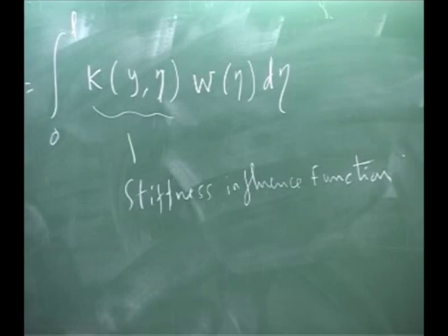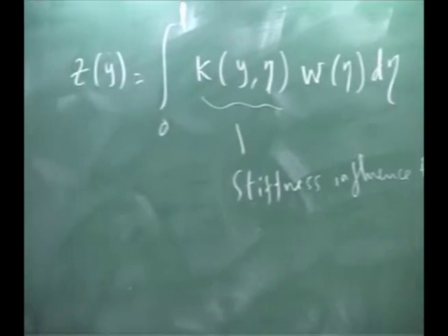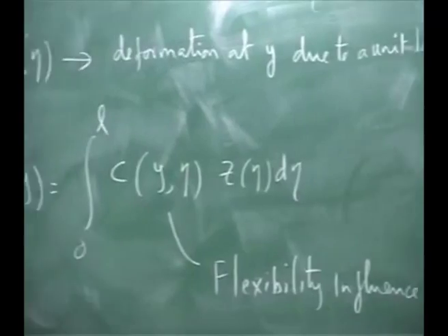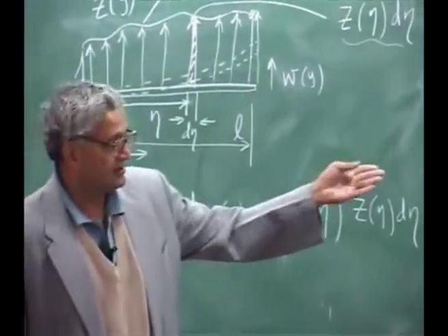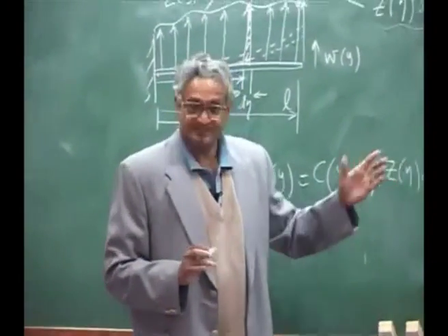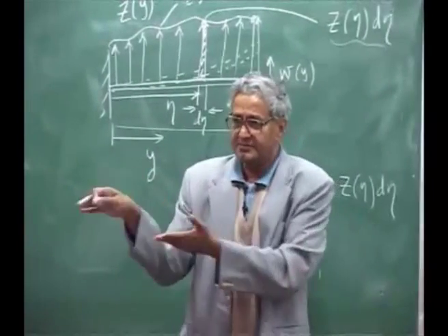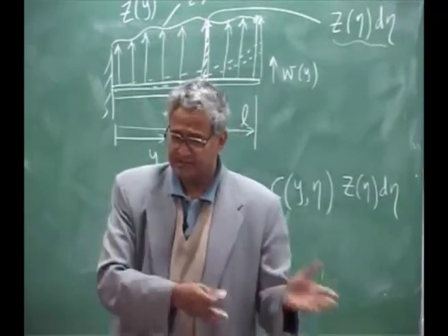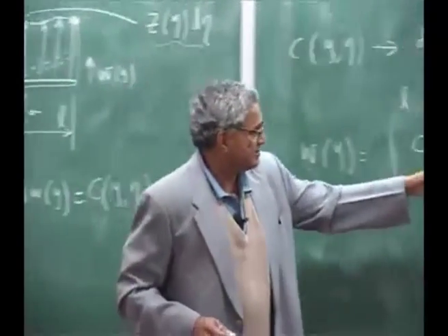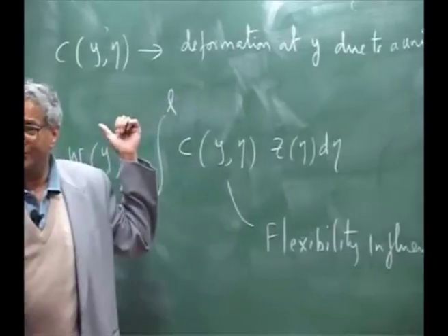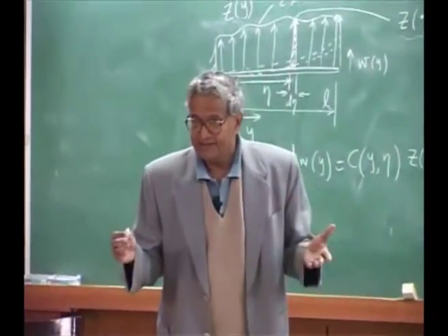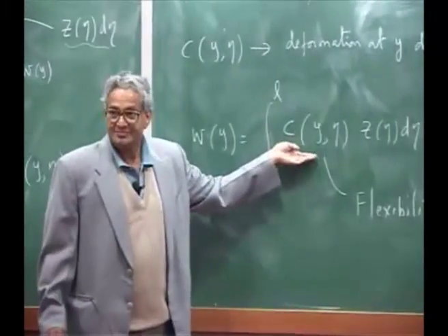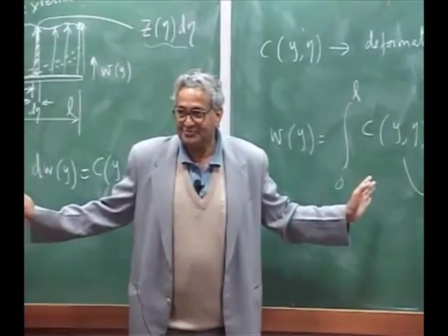Okay, discrete system it is easy, but for experimental measurement you will always find this flexibility influence coefficient is easy. You can go take a wing, put it on a test rig, put suitable boundary conditions, and then apply the load, and then keep making measurements at every point. You can form the matrix because you have to make a grid, and then you can get this. Then you can have interpolation. Now you see, this is how the structural deformation is measured. Suppose you know the pressure on the aerofoil at various points, because this is what either CFD calculation or any other calculation gives. You know the pressure times some area, that is the load. Find out the deflection, you know what is the total deflection on the entire wing. But now the question is, how do you get this? Okay. We have given everything in terms of just mathematical form.